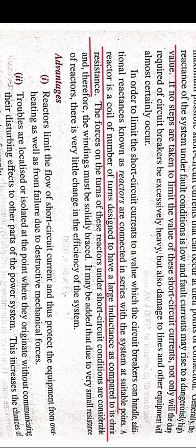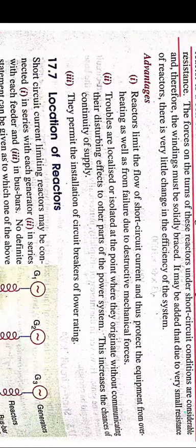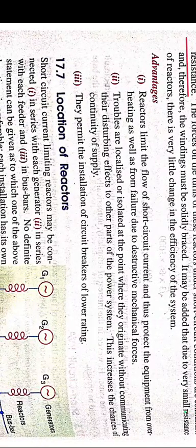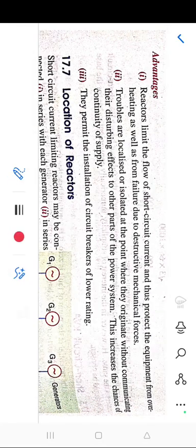Reactors have very small resistance and large inductance. It may be added that, due to the very small resistance of the reactor, there is very little change in the effective system under normal condition. The reactor limits the flow of short circuit current.